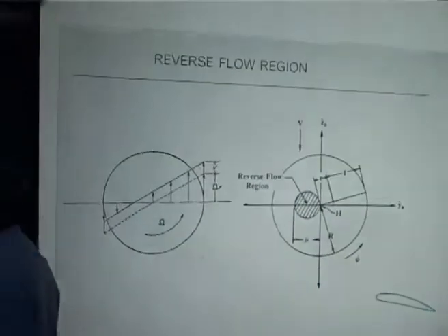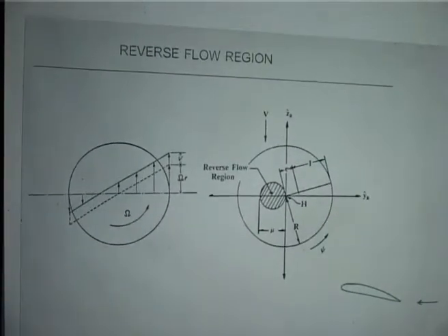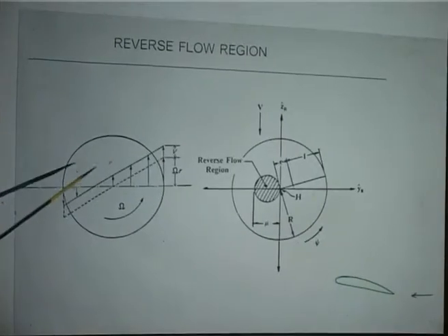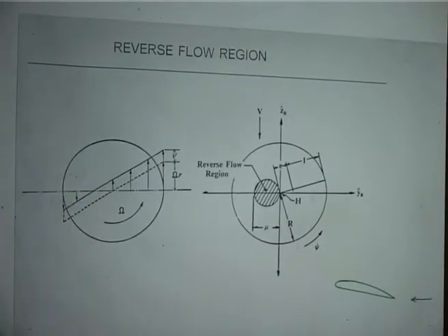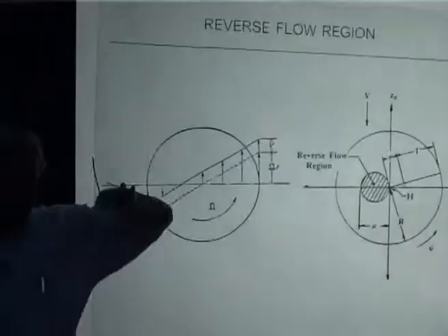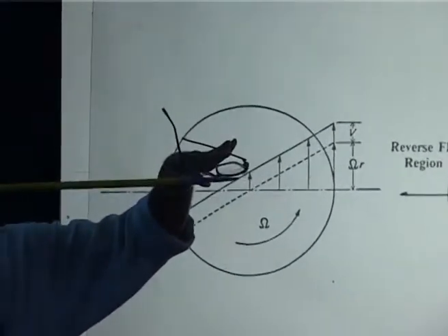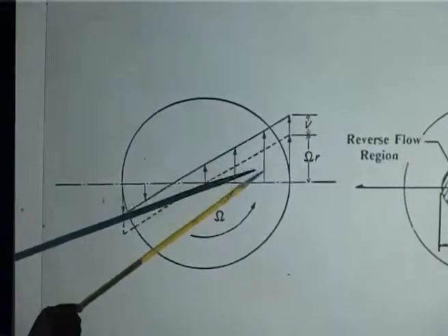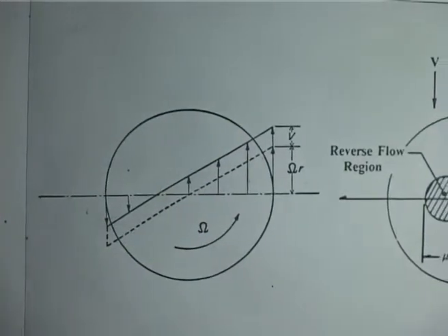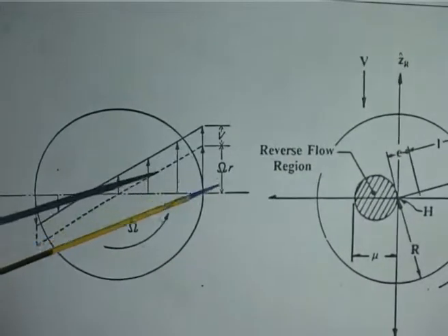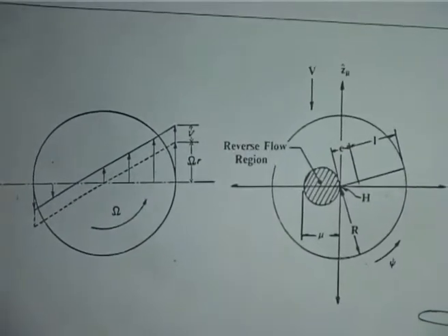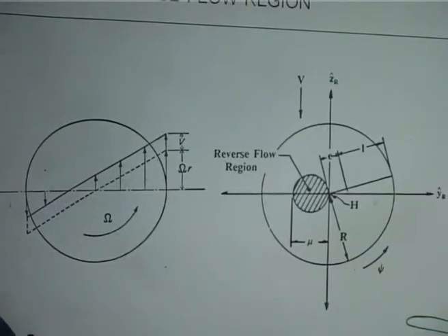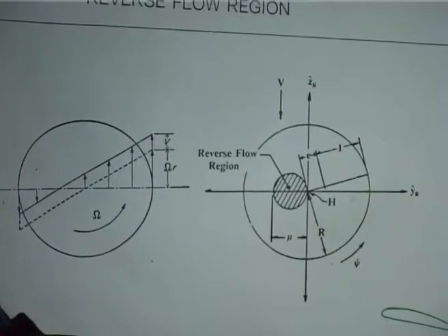One of them I just want to show. This is something which normally does not happen in aircraft. That is why I am putting this. This is the rotor disc. Okay. If it is in hover, hover means the helicopter is stationary, wind is not blowing, you are just above. Omega r is the velocity of the blade, and that is equivalent to relative air, omega r at any section. It is coming radially, that is normal to the leading edge, you can say.